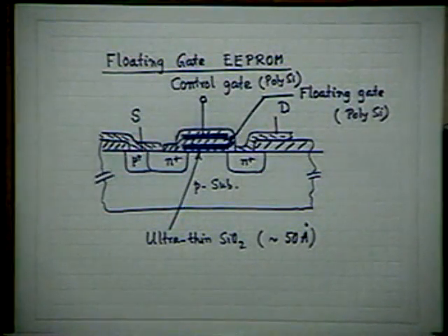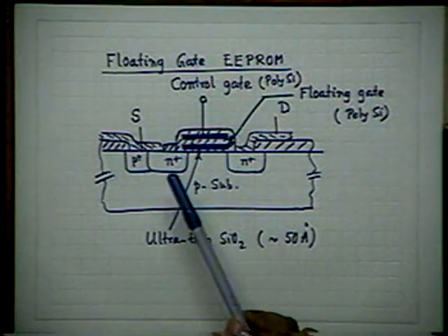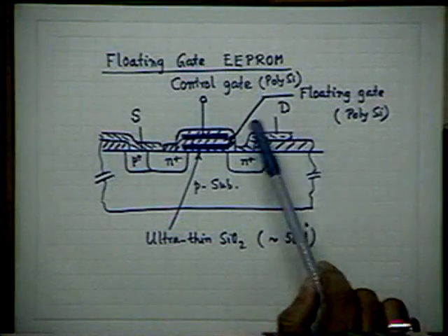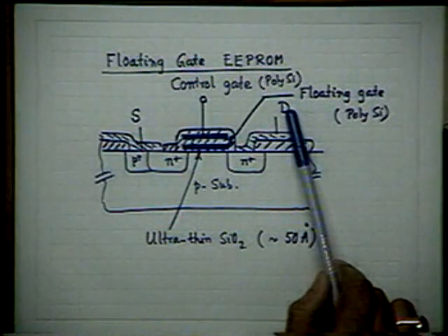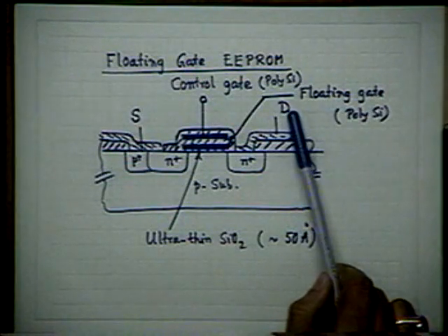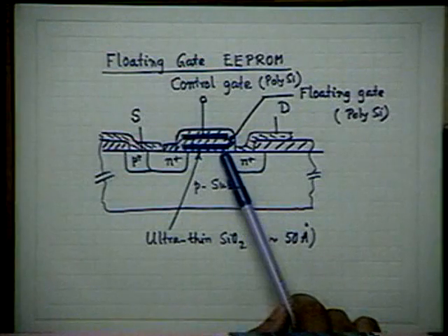Floating gate is shielded, but control gate you have to apply a suitable bias here. Tunneling, sometimes you know that to affect the tunneling more appropriately, we also do it through the drain also. We apply now, what is the polarity of drain bias we apply? Positive. So this junction is reverse bias, there is a strong field here.